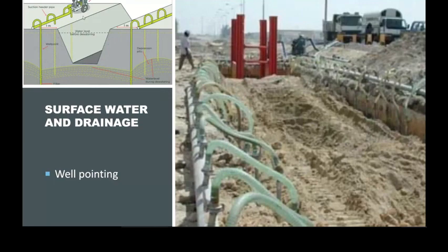And that runs flat out, and it's a pump that's designed to run all the time, or basically run dry as well. It sucks the water out non-stop, and then you pump it out to an area away from where you are, like another stormwater sump in the road or something, that's not going to come back in. So it just has to run all the time so you can do your job, to stop it floating your pipe, and also so you can get in the trench without being saturated with water.